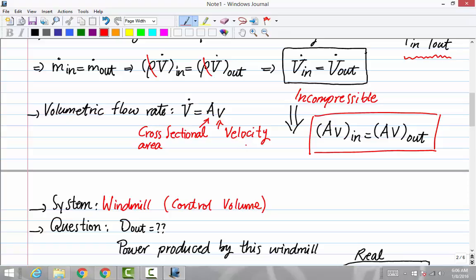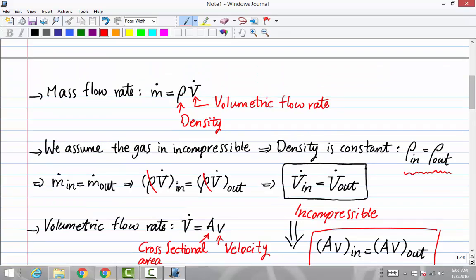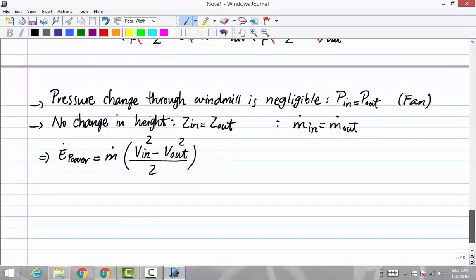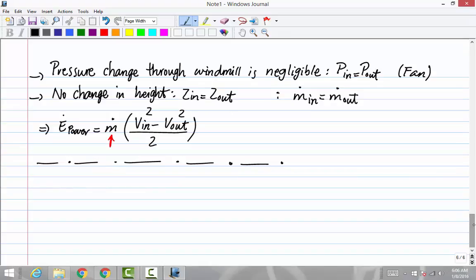In this case, we have the cross-sectional area, the diameter, and the velocity at the inlet, but we do not have the density, right? So m dot equals density times V dot. And here I need m dot to plug it in there. So I need to pause for a second, find m dot, and then come back and plug it in there. I know that m dot equals, as I defined it for you before, rho times V dot, sorry.